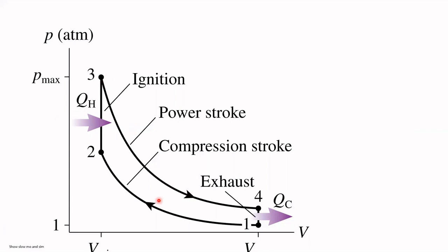Now, before the spark plug ignites the fuel-air mixture, the air is first made to be very hot. So we start over here at point 1. The pressure is 1 atmosphere because you draw in air from outside the vehicle. There's that intake manifold, and maybe it comes in a little bit warmer because it's already flowed over engine components, but it's basically the outside air temperature. Let's call it room temperature.